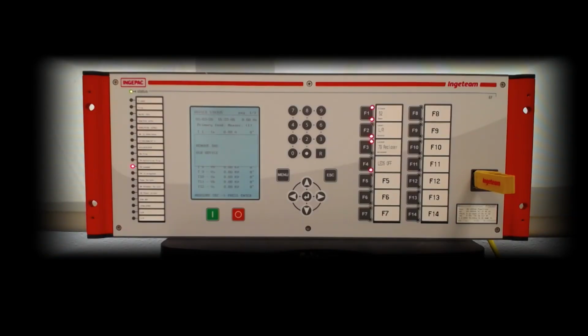After uploading the firmware update file, the IED will ask the user to unplug the USB drive, action after which the firmware update will begin. In IEDs with a local display, it will show a progress bar for the update procedure and the status LED will start blinking.